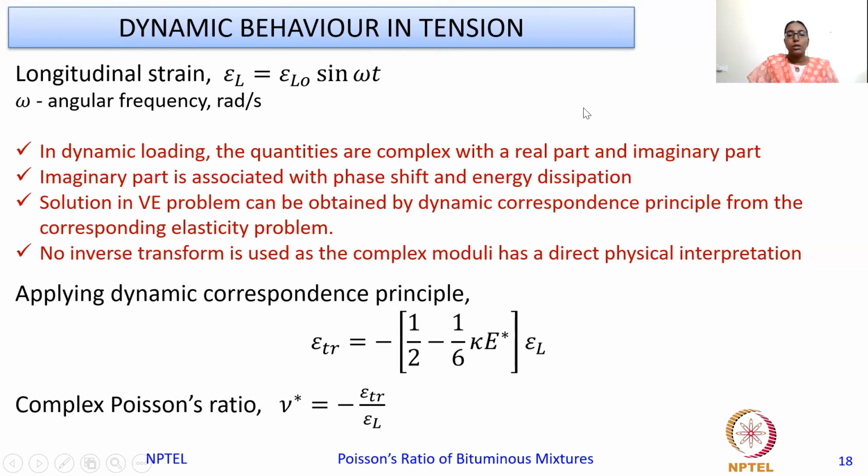Now, in dynamic loading, the quantities are complex in nature, which will have a real part and an imaginary part. Now, the imaginary part is associated with the phase shift or the phase angle and the energy dissipation. As we already mentioned, the solution in the viscoelastic problem will be obtained from the corresponding solution in the elasticity problem.